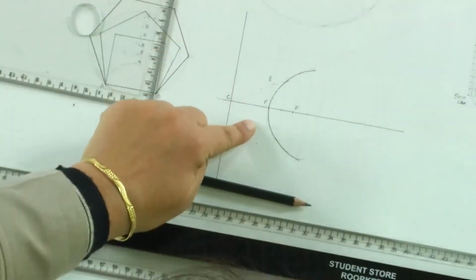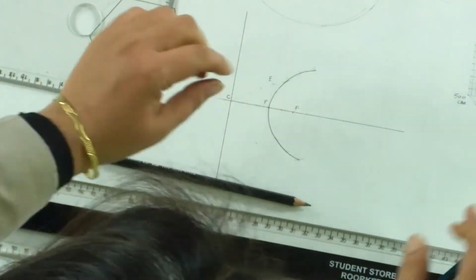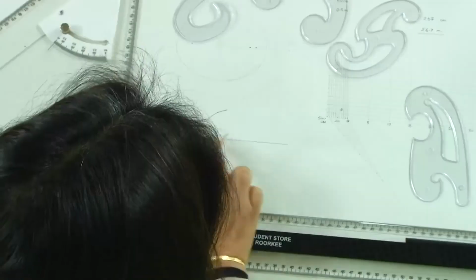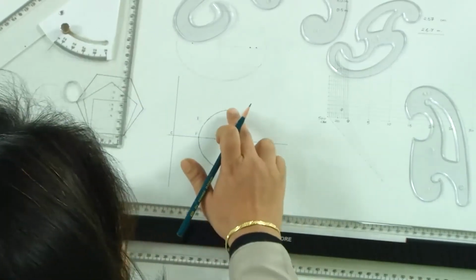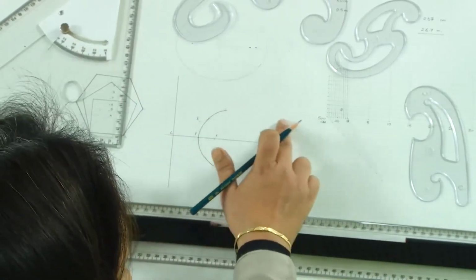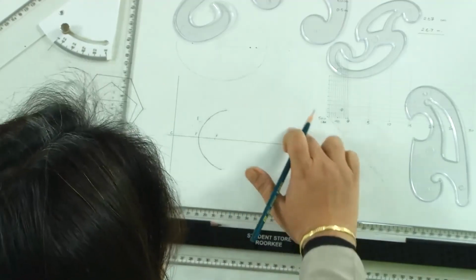That's how we fix the curves on an ellipse using these French curves. It could be any of the curves which could fit, but then you have to remember the number which has to be repeated on the other side. And just like this, if you continue to develop more points like this, you will get other points on this ellipse, and it will become a closed curve.